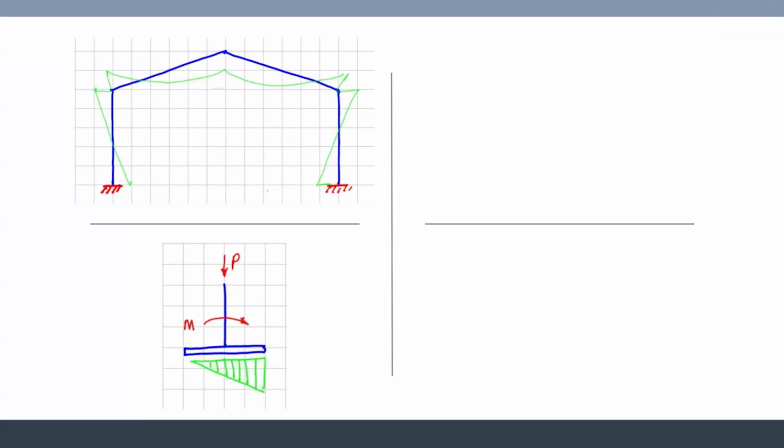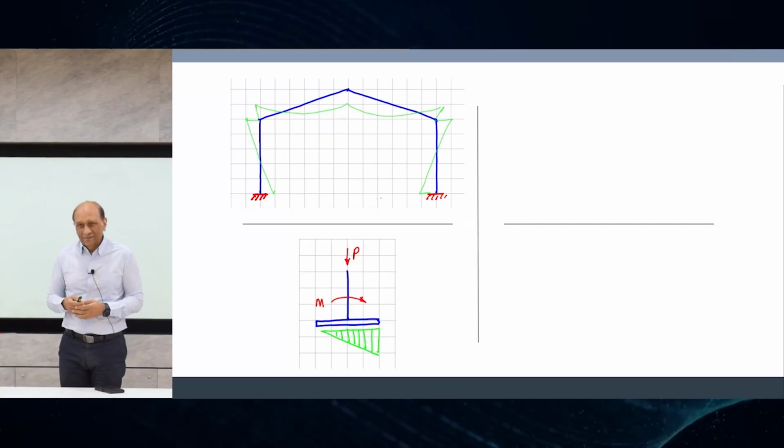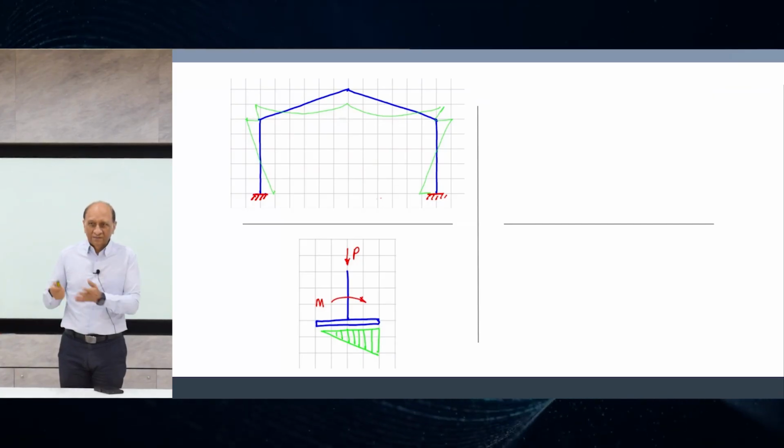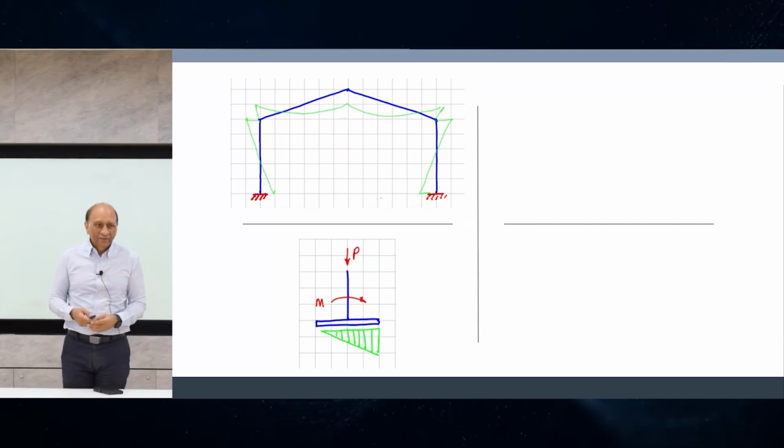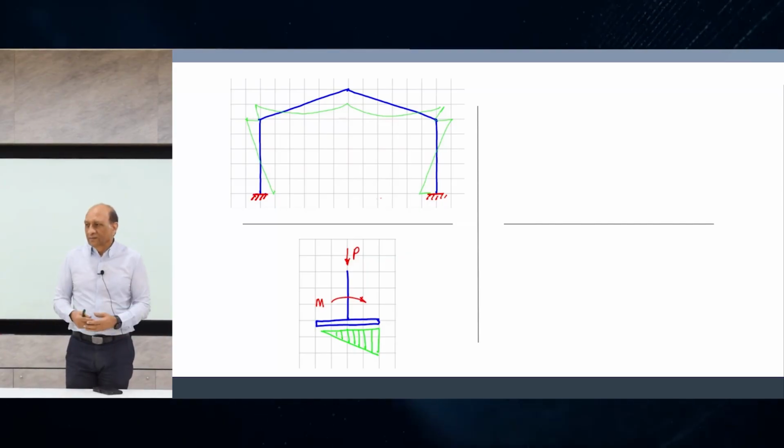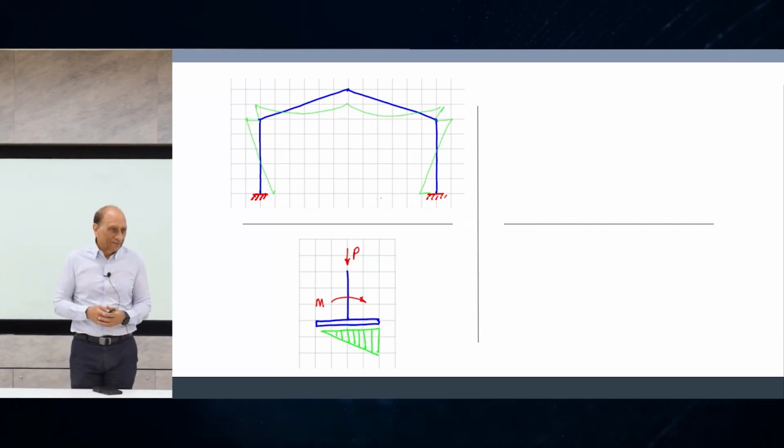And then the problem is that when I tried to design this foundation, I just could not design it because the moment keeps causing a large soil pressure on one side and uplift on the other side. So I kept increasing the foundation size until it went outside the building, the site limits. It becomes so huge. So I took that foundation to my supervisor and I said, this is funny because it's a small building, just one story, and the footing is so huge. Nobody will make it. People will think I'm crazy.